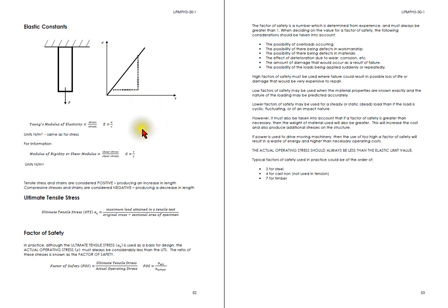For us, we are only going to be studying for structurals really. Ultimate tensile stress does creep in, but we're only really studying it up to the elastic limit, and the Young's modulus tells us that if we take the stress divided by the strain, the more force I pull with, the more distance it gets extended, so the stress over the strain equals the Young's modulus.